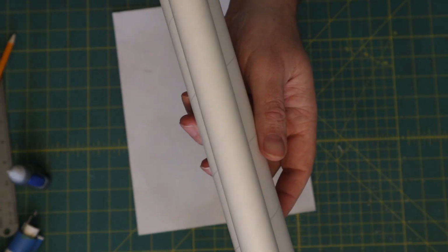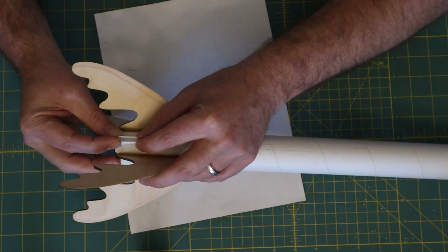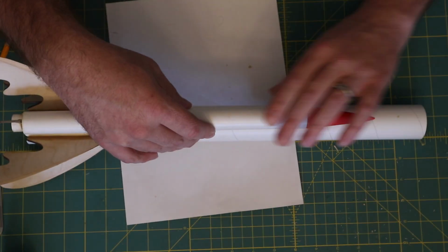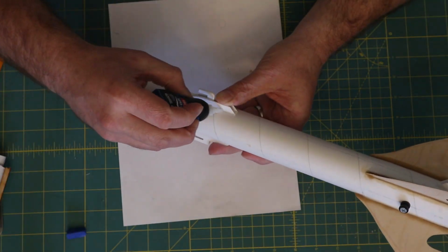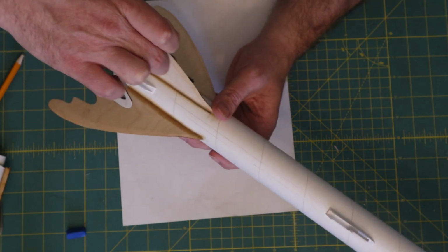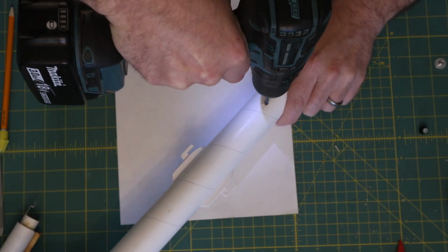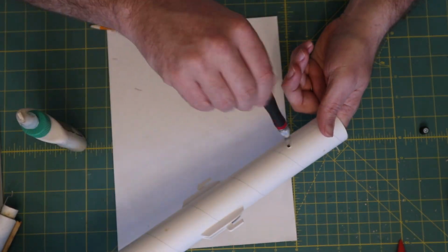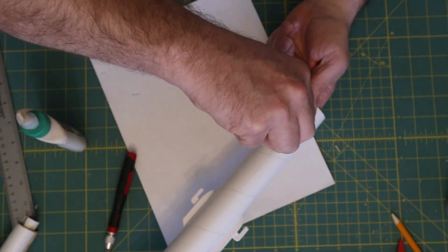We'll put some glue on the top of that hook, and we'll put it into the nose cone and lever it down. We do have lines marked to make sure that these are nice and parallel with the rocket body. And again, what happens here is the nose cone will come off, and that releases the hook on the top, and then given the drag on the open end of the booster, it'll then fall away nicely, pivoting around that bottom mount.